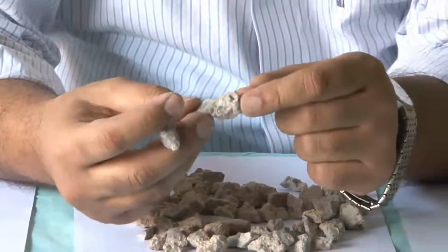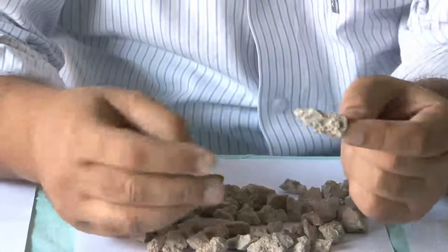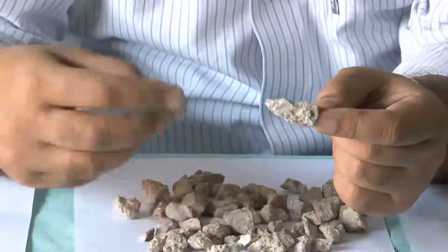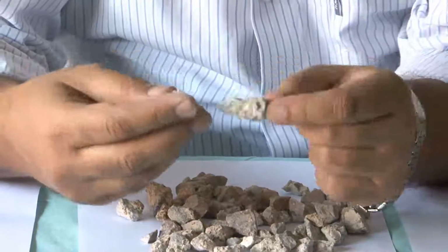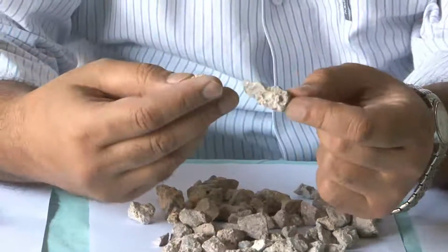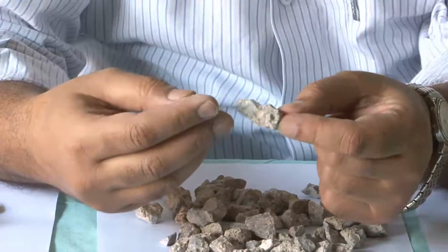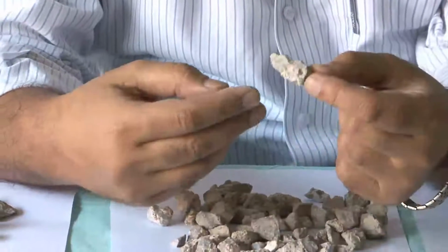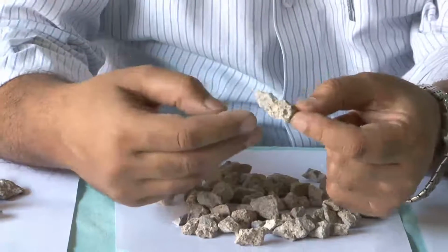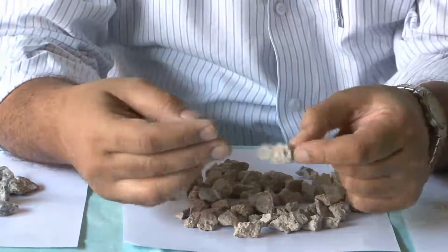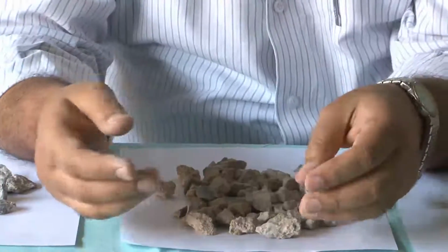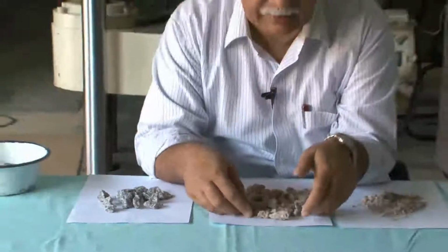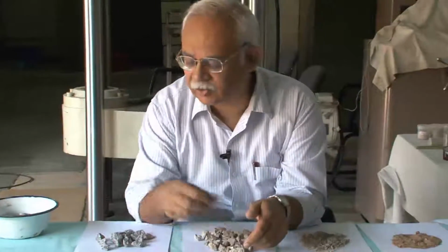What happens as a result of this adhesion of mortar in the case of recycled aggregates is that the water absorption of these coarse aggregates increases. The properties of the concrete that we get if we use recycled concrete as coarse aggregate will be different, in terms of strength and so on, because the strength of these aggregates in a certain sense is lower than the strength of these crushed stones.